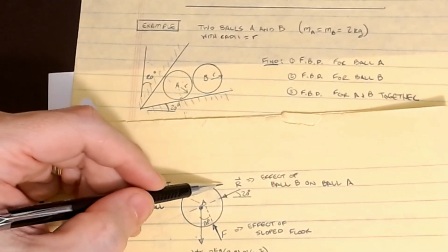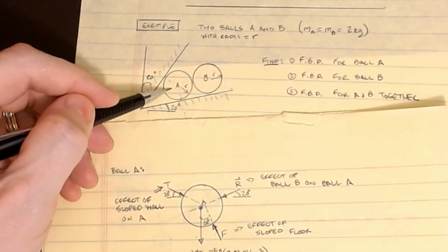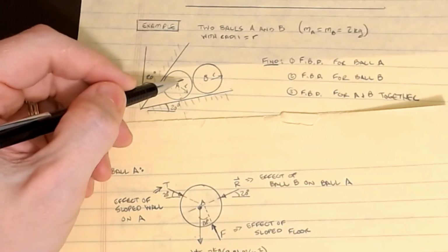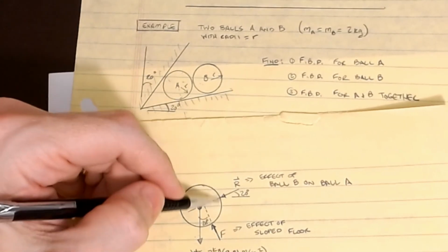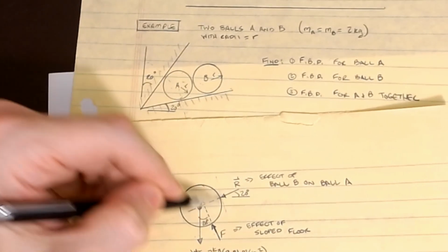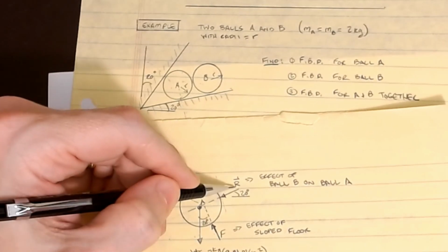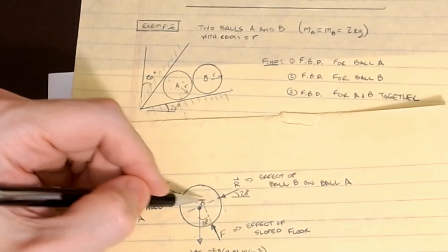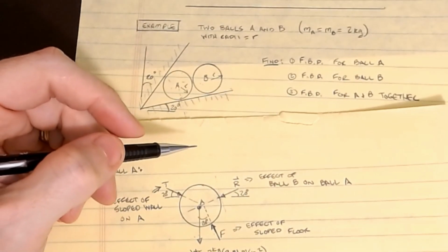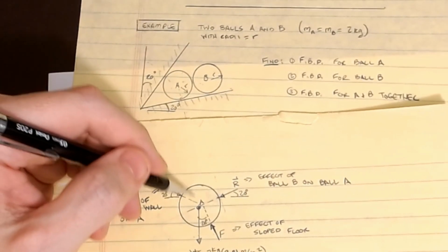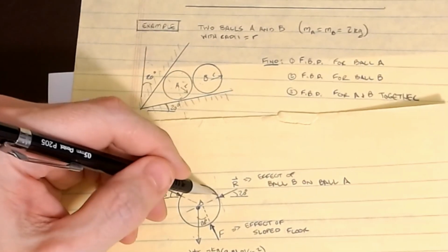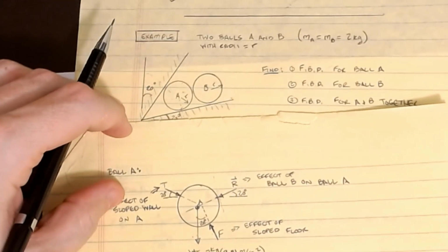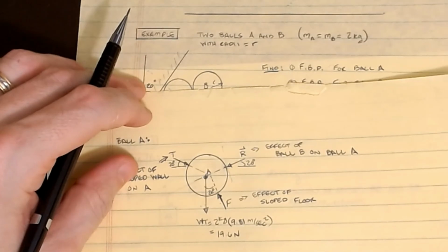Okay, but if I pull this ball A out, there's also a contact force that exists between B and A. That means that if this is my contact plane, perpendicular to that is this R force, and it's also at 20 degrees, and it's also pointing back to the center of the sphere. So that's the trick for these sphere objects or these circular roller objects: all of these contact forces point back to the middle of our object. That's why I wanted to show you this one. It's kind of interesting as we look at that.